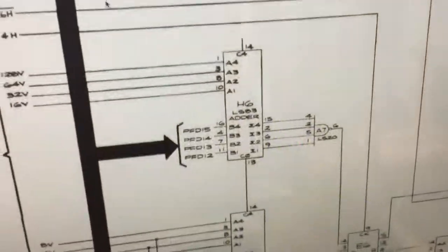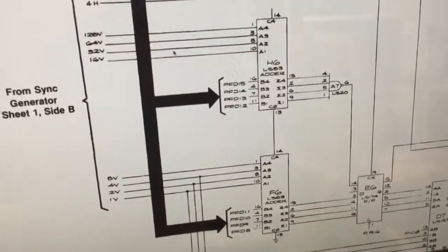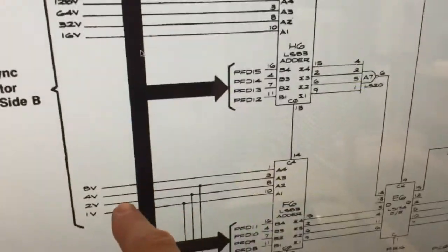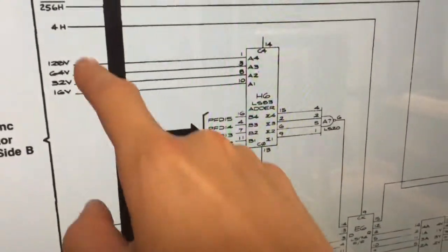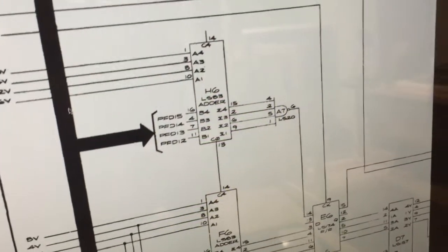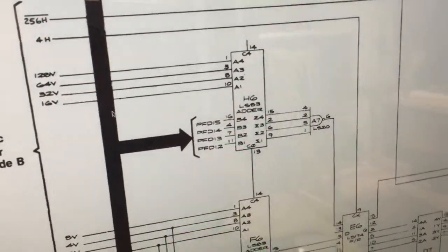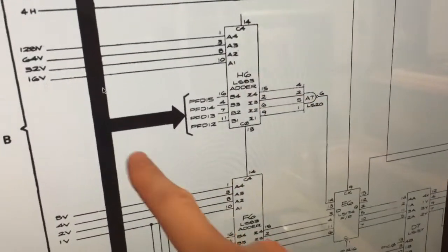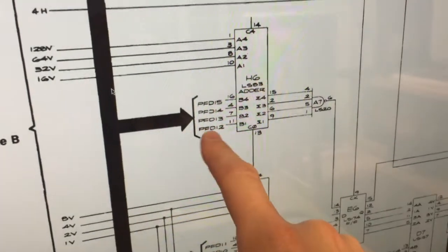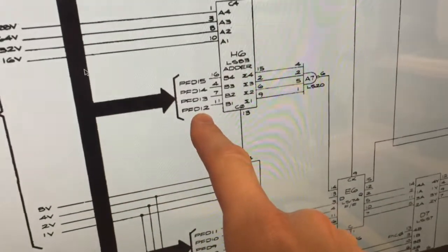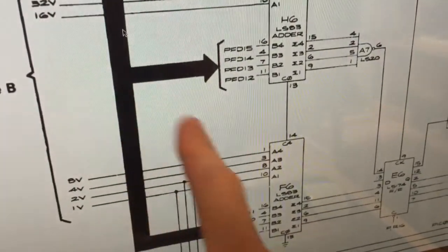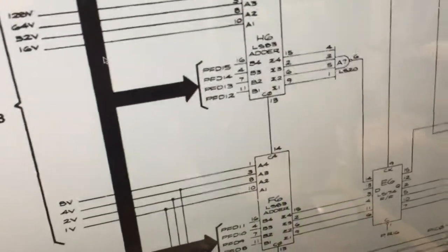Okay, and here's what the beginning of the motion object circuitry looks like. It's actually a very common architecture. This is the vertical position signals, and they are going into two multiplexers right here, and as alternatively selectable input signals, we have a connection to the playfield data signals, which are coming from the CPU.